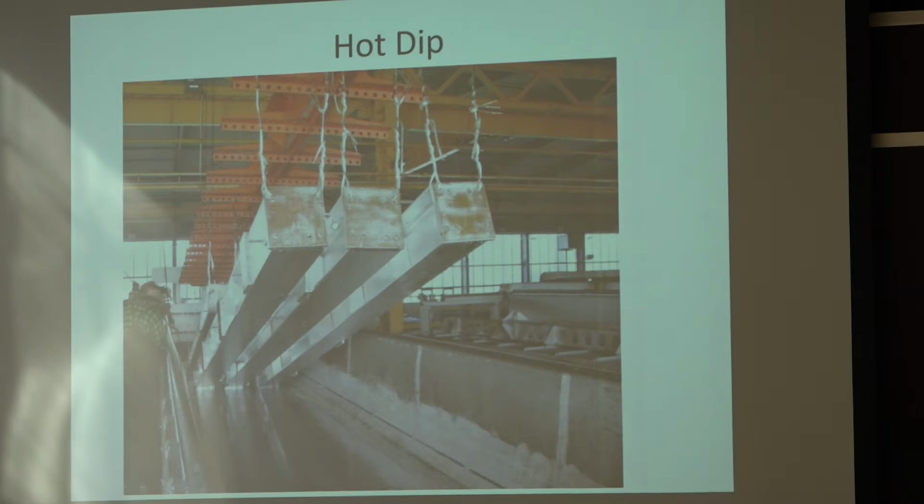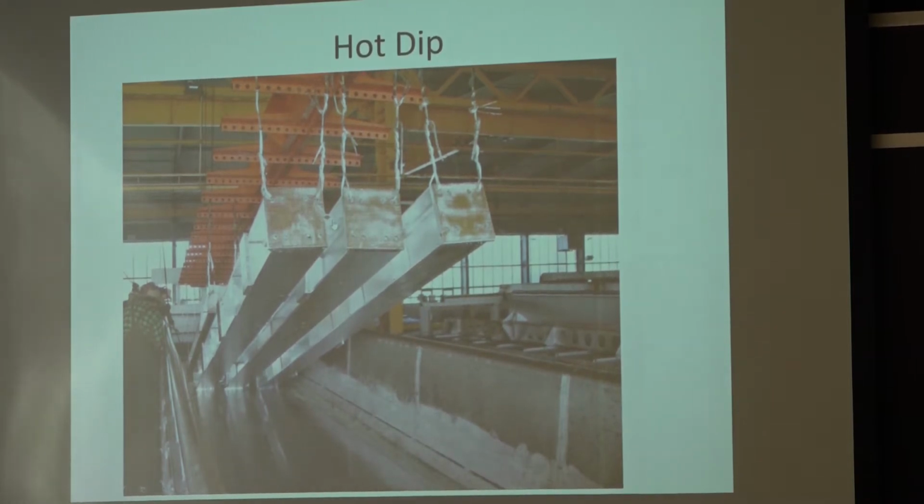You clean those surfaces before, so a lot of times there's steel fabrication, it's stored outside, it gets a little rusty, it gets thrown in an acid bath for cleaning, and then it gets galvanized. What is interesting with galvanizing is, so long as that acid cleaning is done correctly, there's not a lot of issue about the zinc falling off the surface.